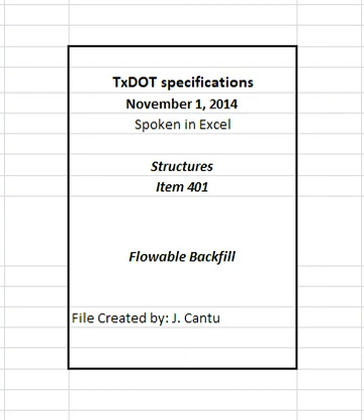2.3 Chemical admixtures. Furnish chemical admixtures in accordance with DMS 4640, chemical admixtures for concrete. Use specialty type admixtures to enhance the flowability, reduce shrinkage, and reduce segregation by maintaining solids in suspension when necessary. Use and proportion all admixtures in accordance with the manufacturer's recommendations.